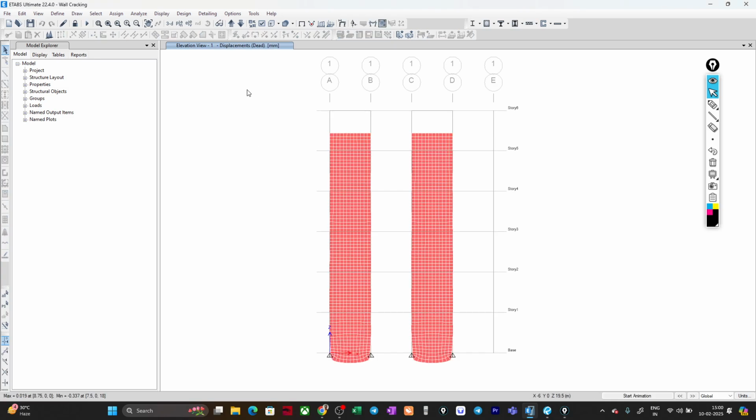Okay, so it is very clear that when we talk about the axial load, this wall has a huge height. So the moment of inertia for the vertical direction is huge, correct? So we do not have to check the stresses for that particular case. Our load applied is in the lateral direction, so basically we'll be checking the stresses for the in-plane bending action, right?